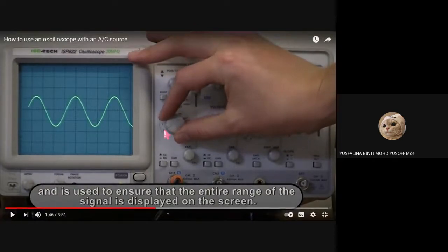So for this one, it is 2 volt per division. Just now when it pointed at 1 volt per division, 1 division was 1 volt. Now it goes to 2, so 1 division is equal to 2 volt here, right? So I repeat again, just now 1 volt per division means 1 division is equal to 1 volt. Let's say it changed to 2 volt, it means 1 division here is equal to 2 volt. So that's the difference.